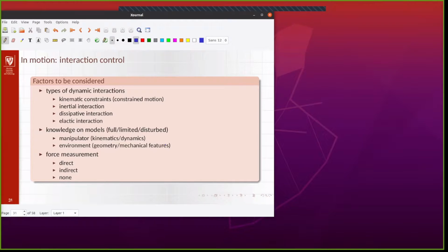So when we see a flat object and we are just approaching it, and we want to predict what will happen after a contact with the robot, we need to know if it's a concrete wall or it is, let's say, a sponge that will not be noticeable by the effector. So geometry, but also mechanical features, which means the elasticity and the reactions to the forces.